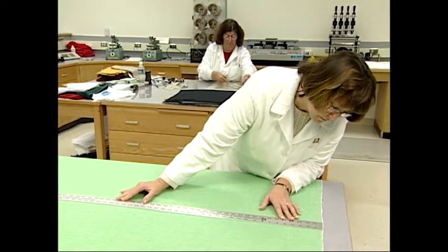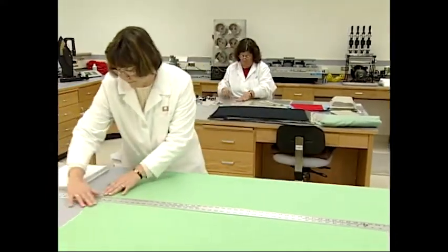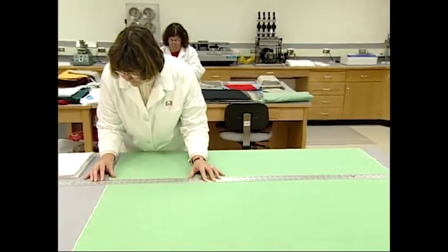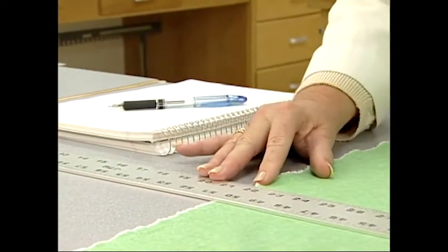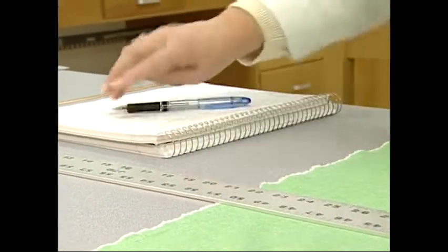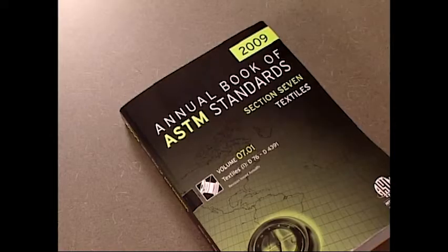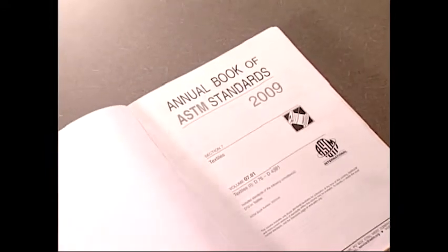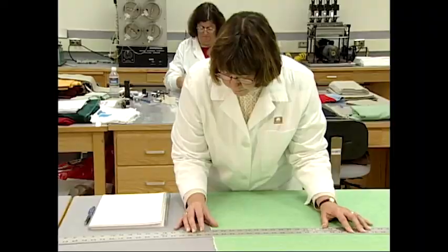The accurate measure of width for a fabric for cut and sew processes is very important. The efficient allocation of markers for cutting is based in part on the usable width of the fabric. The measurement of width must take into account the type of fabric, whether woven or knit, and the type of selvage. ASTM test method D3774, width of textile fabric, gives 2 methods of determining the width of a fabric.